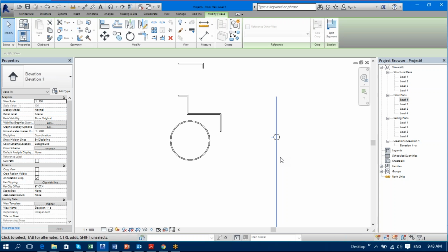The second thing is, I don't want you to always use your mouse and click here. Underneath the create panel, there are 4 construction modeling tools. These are 4 construction modeling tools for you to work in a precast facility when you are making different panels. These 4 construction tools are among the most important for you. Right now you would be using just this part of the construction tools called groups, right? But these groups can be used very innovatively.